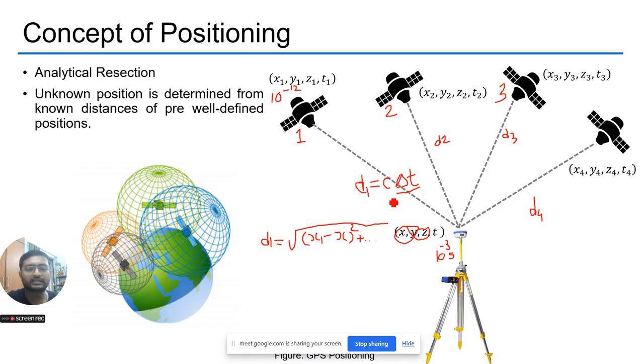So we need another parameter to solve this satellite clock error. And that's why we need at least 4 satellites, to avoid the satellite clock error. If you have heard of the error budget, the error coming from the satellite clock is the largest, which is around 5 to 7 meters.